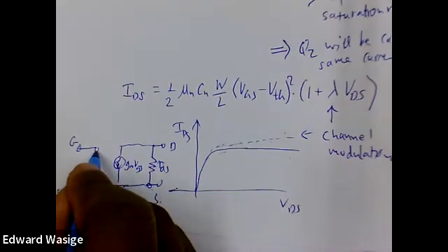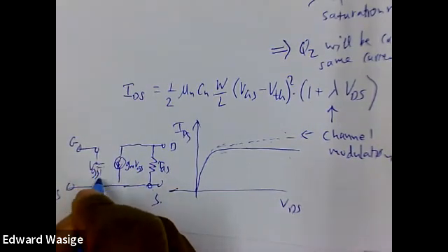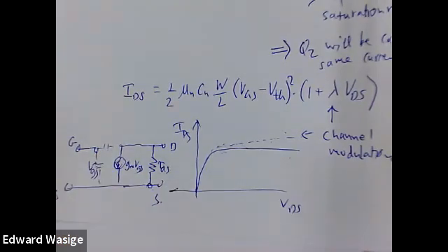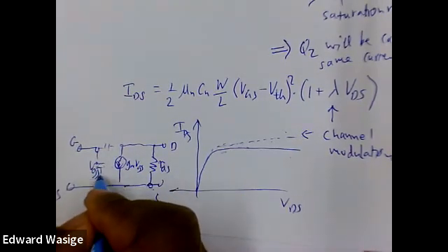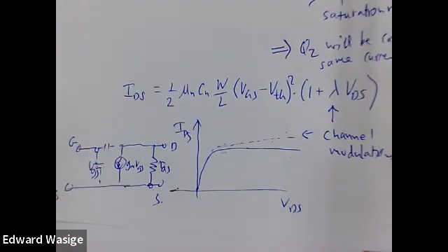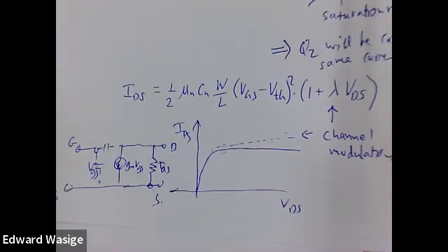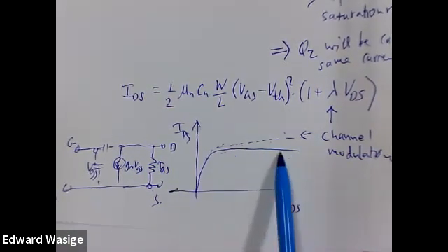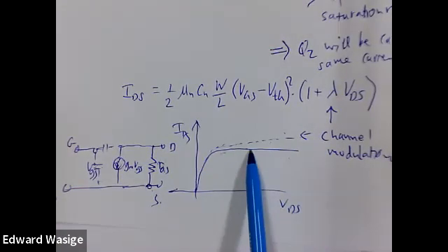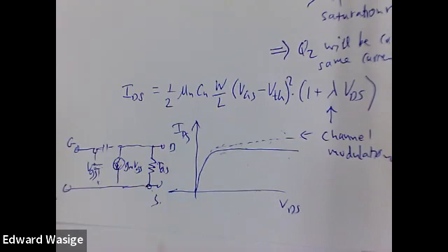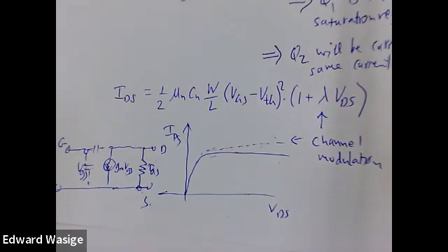If the frequencies are high, of course, we can include the capacitors, but for lower frequencies, we don't need to include the capacitors. So for most of the work we do on this course, in terms of amplifiers, we're not looking at high-speed amplifiers. So gm·vgs and rds are an adequate representation. Often for rds, we assume that the drain current is independent of VDS, so we can ignore that as well. But if we consider it, we can have a large value of rds at that point.